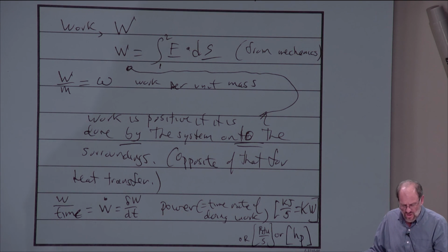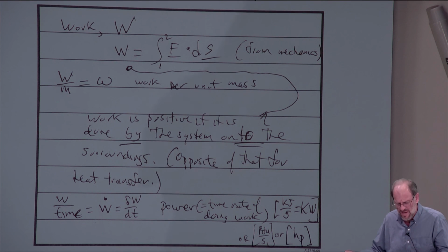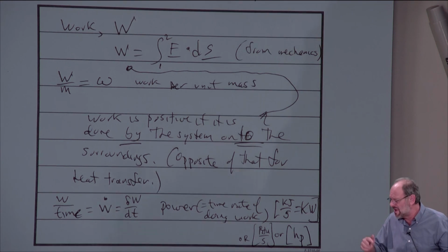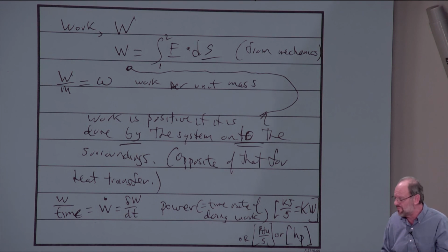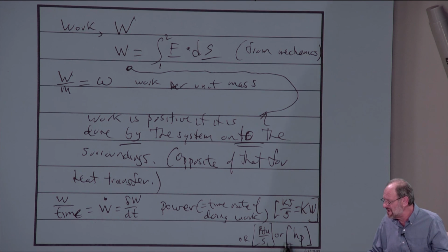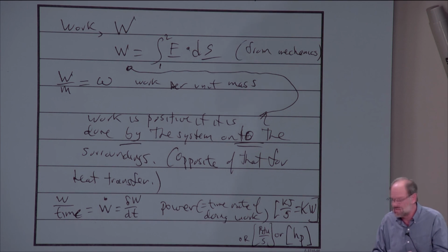I can't tell you the exact numbers. It's something like 1 horsepower is about 0.71 or thereabouts BTUs per second. But you'll have to look up the conversion factors. So if you're solving a problem and you're using traditional British system units, you're going to somehow have to convert from horsepower into BTUs per second, or maybe into BTUs per hour, or maybe even into foot-pounds force per second or foot-pounds force per hour, just to get all the units to work out properly.